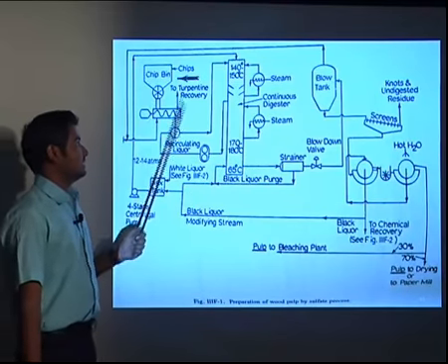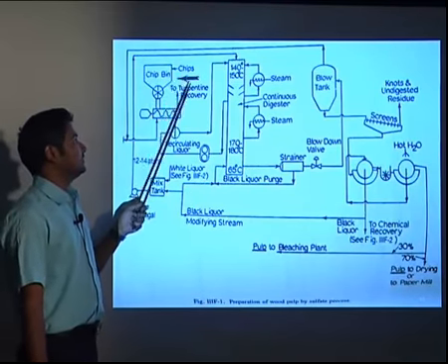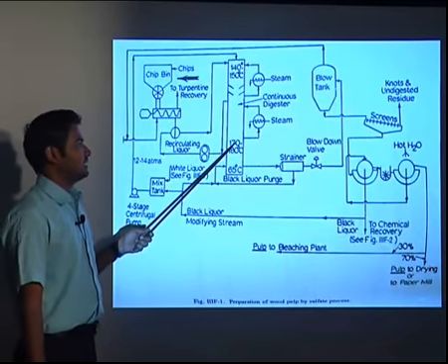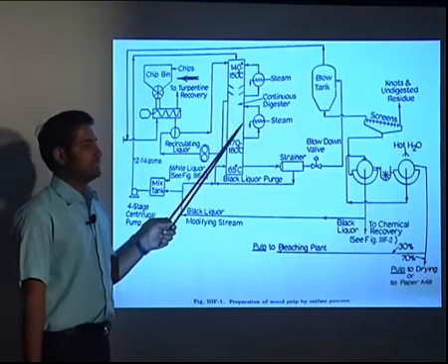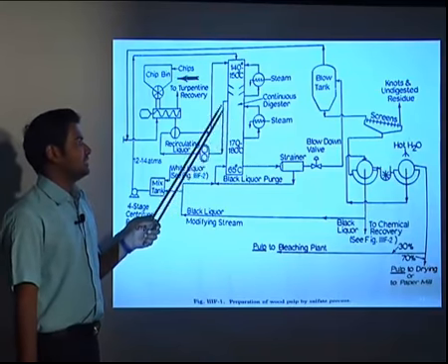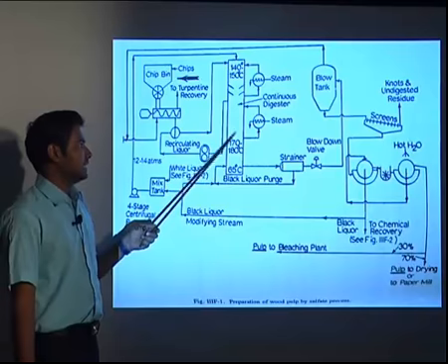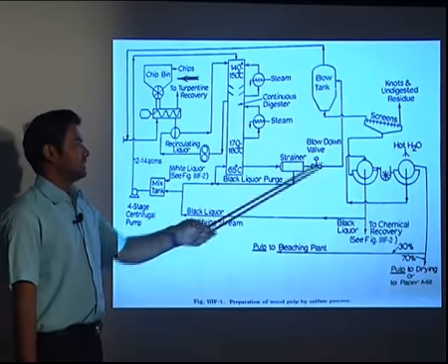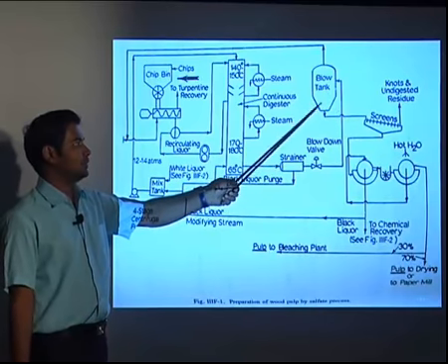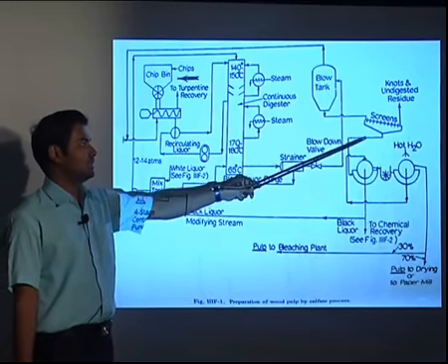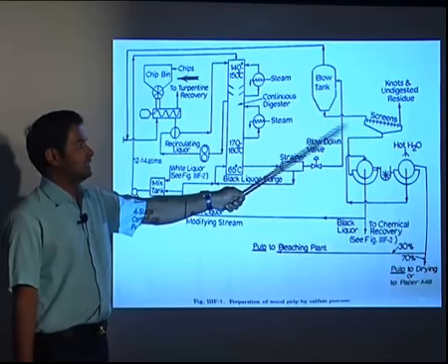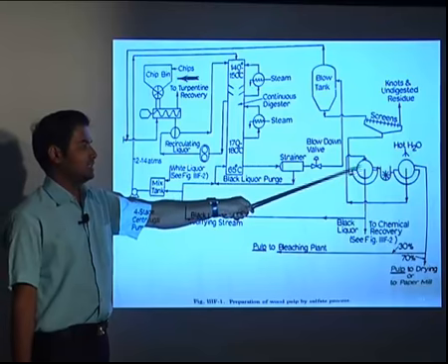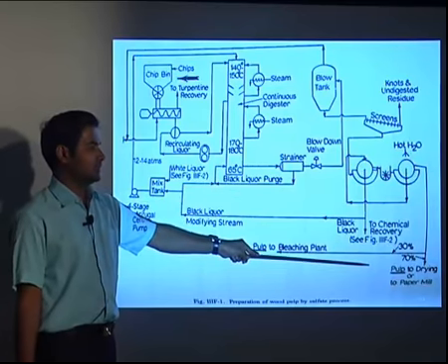So in short, the wood material will come, and it will be shredded into very fine particle size. Then we add the chemicals in the digester mixture, and we maintain the temperature, so that the wood becomes softened, and it will ooze out the lignin material and other non-cellulosic material. Then the cellulose material we send to the blow tank, where the water will be removed, and then after screening we can dry and press them, and the cellulosic material will be sent to pulp drying.